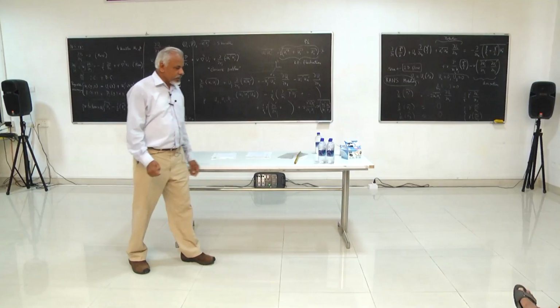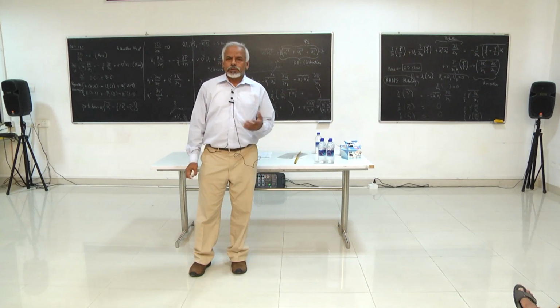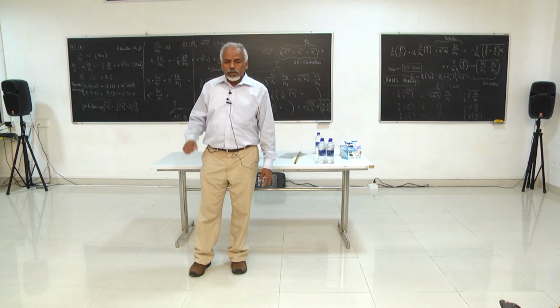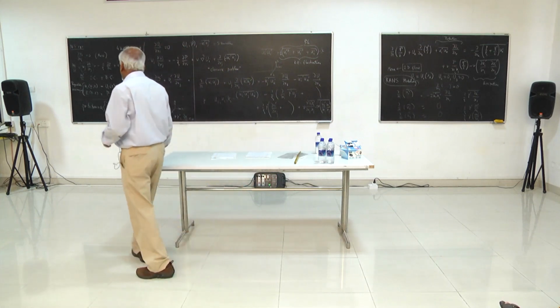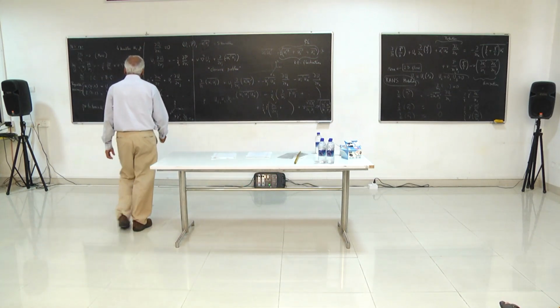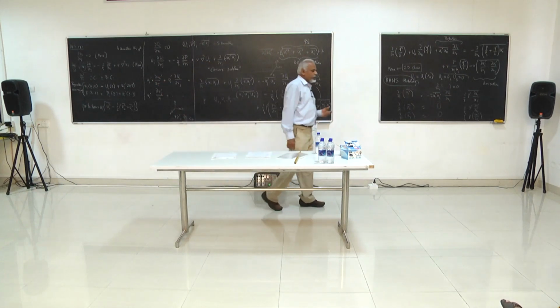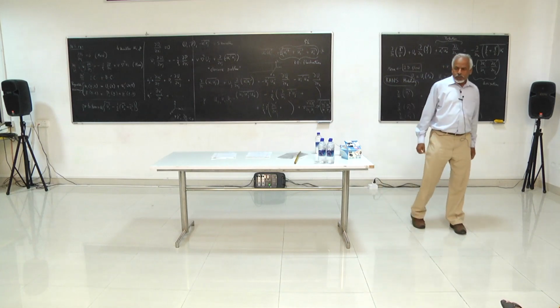All fluid properties change very rapidly. Anything like kinetic theory or the Boltzmann equation is not valid, but this one appears to be valid even there very nicely. And furthermore, the Boltzmann equation is valid for, let's say, rarefied gases, but this, of course, is true for liquids, true for everything else that you can imagine, flows of that sort.